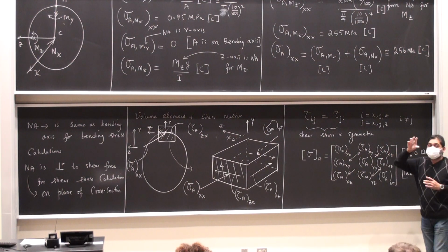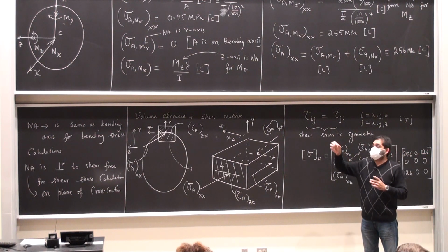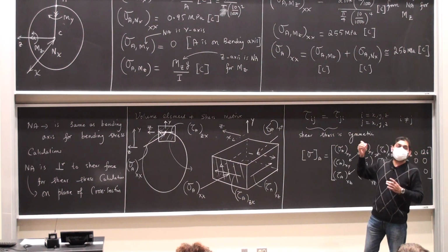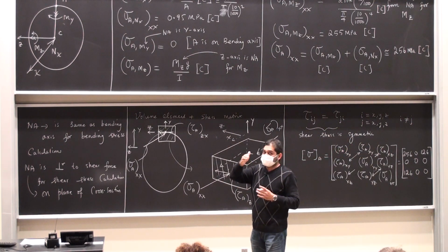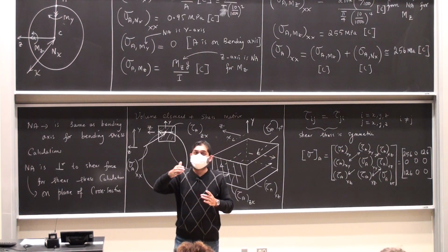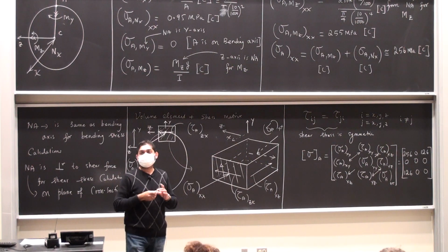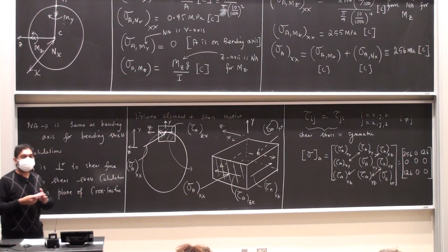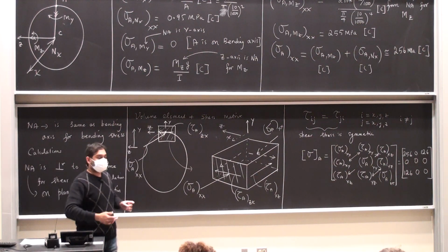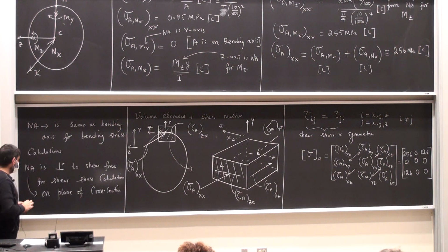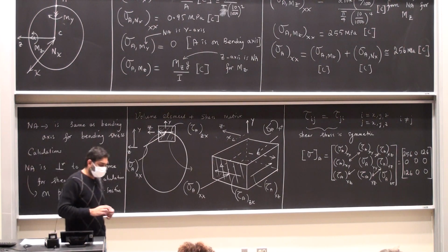You can write the same set of matrices for different other points, point B, point C, point D, find the eigenvalues of those matrices. Whichever gives you the largest value of the stresses is the culprit. That's where your failure is going to start. That all belongs to what is called a static failure theory. If you're taking machine elements, you'll come to know about it. So we will not be doing that in this class.